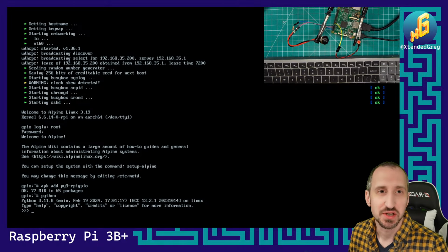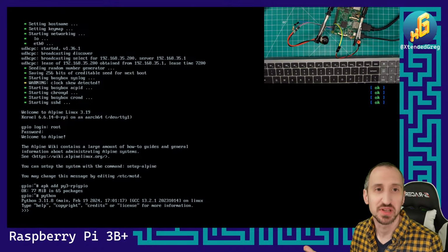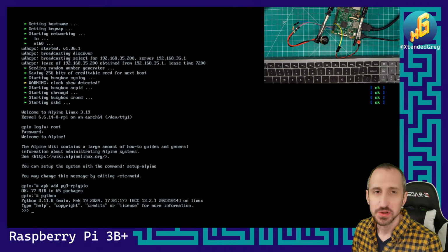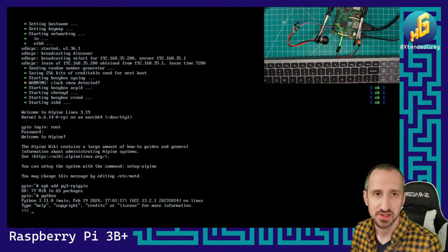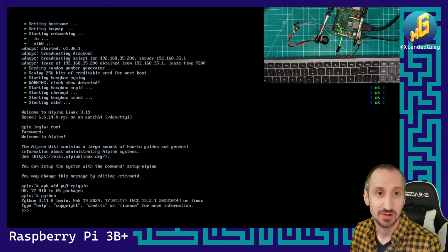So first, let's actually just go through a basic example. Okay, so we want to take a look. We want to light up an LED in a repeating fashion and just blink it, the standard blinking LED. So the first thing that we need, because we're defining this just like we would a Python script, is we need to import our GPIO library that we just installed.